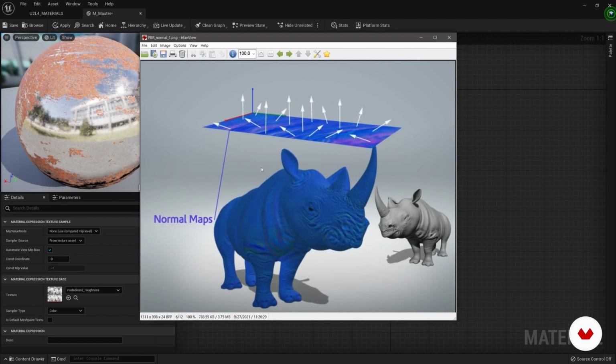Normal maps work like in any other 3D software. It's those two-dimensional maps which give the illusion of micro details on a mesh, without necessarily increasing the number of polygons. It is a two-dimensional map that maps to the UVs and gives this illusion of micro details. It works exactly like in all other software. Perhaps the only difference could be that working with DirectX, the green channel is inverted.